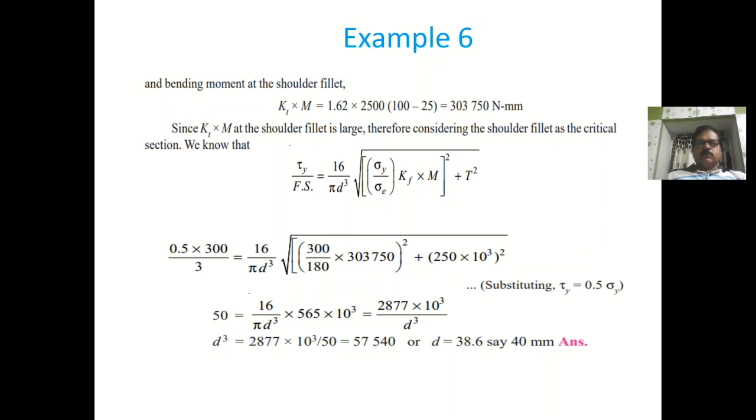The endurance limit is the one: the higher the endurance limit, the more the member resists fatigue failure, and the endurance limit depends upon various factors like surface finish factor, size factor, reliability factor, etc. These are going to discount the endurance limit.